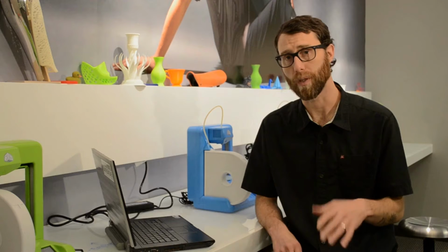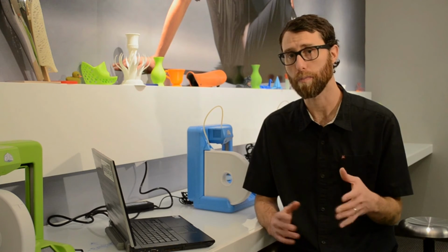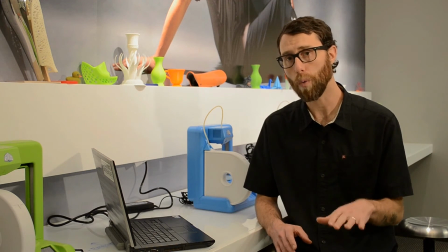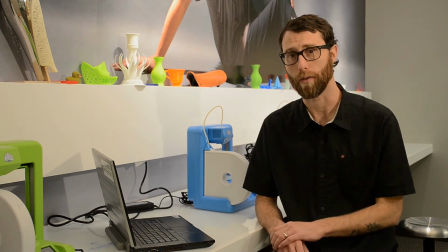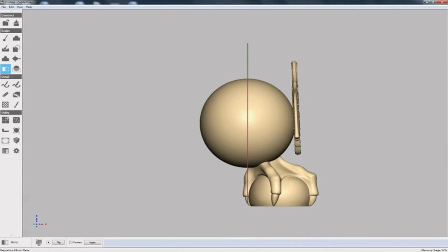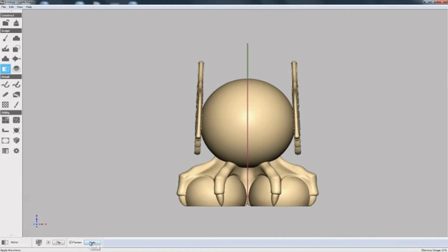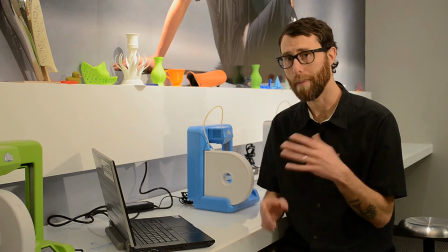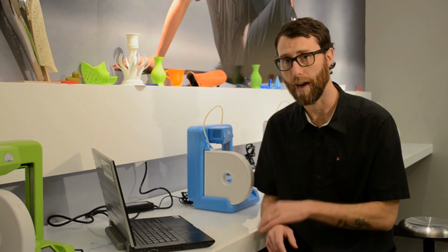Note that in mashup mode, we can support multiple files and freely switch between them for modifications before we hit apply and bake them into the core model. So after I position the foot and hit apply, all the changes are baked in. Now I'll use the mirror tool to copy the changes from the right to the left. I can then sculpt on the mashup model that we've created using multiple files.